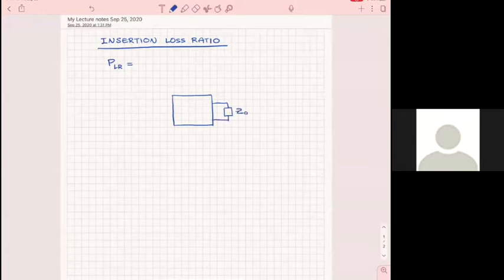The load is Z0, which is the reference impedance. And then you have here your ZS and your voltage generator. And if this is gamma sub I, that is also defined in terms of Z0. Initially, obviously, we are going to consider in our designs that ZS is equal to Z0. So we define this gamma in as Z in minus Z0 over Z in plus Z0, okay?